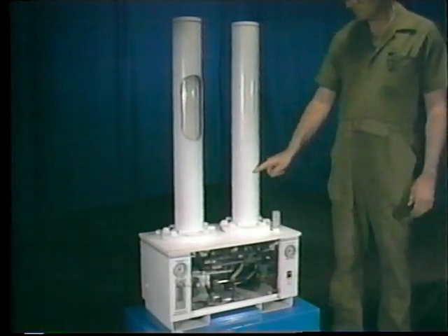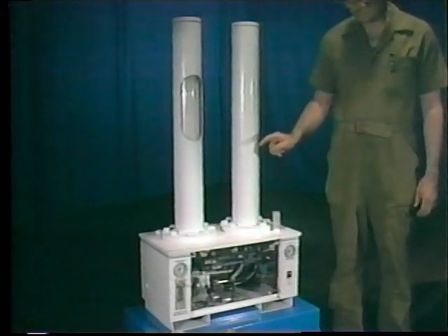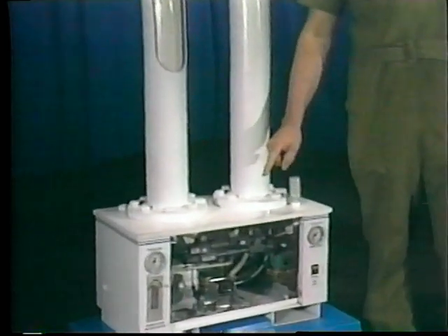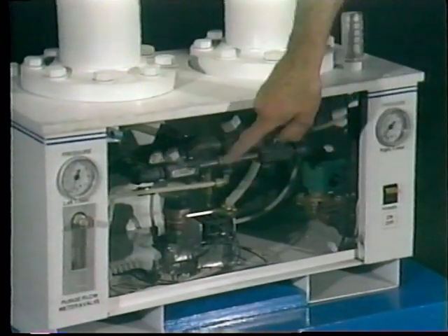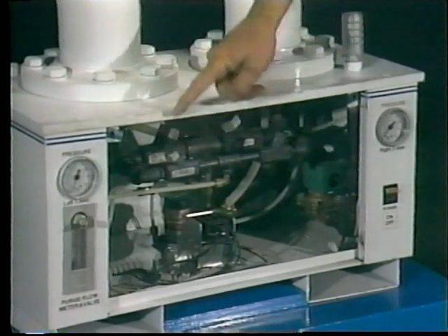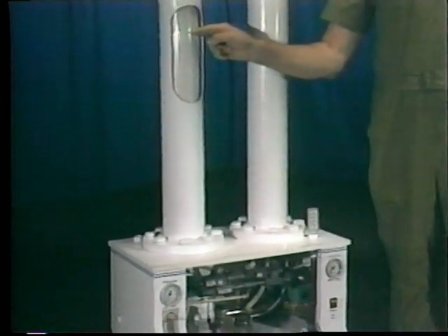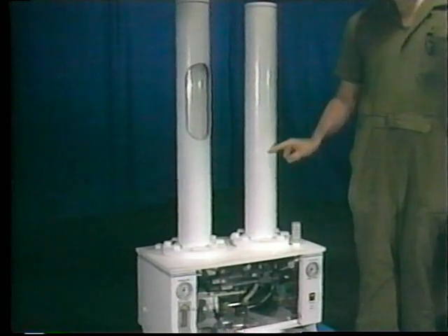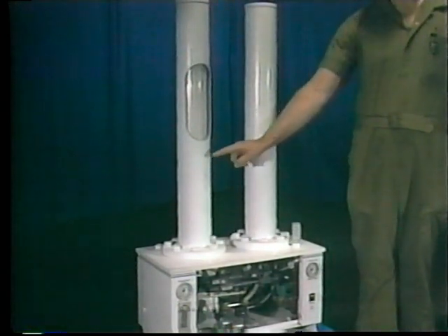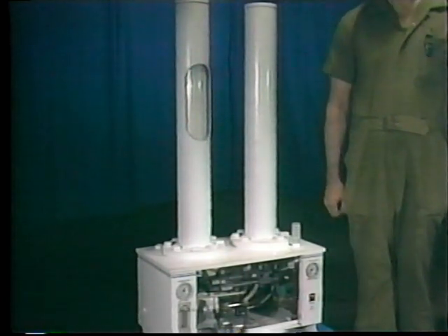While the agent in one of these towers is being used to draw moisture out of the system, some of the dry air exiting from the tower is depressurized back to atmospheric pressure and piped over to the other tower. It is then passed through the agent here and dries it by absorbing the moisture out of it. Then, when the agent in this tower has become saturated, the agent in this tower is dry and ready to be used again. So the unit switches over and reverses the process.